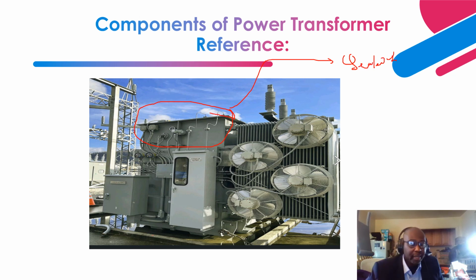As you can see over here, the top of the transformer is sealed, and inside that you have oil. On top of the oil is a cushion of nitrogen that has been put over here to pressurize and create a positive cushion pressure. This is the enclosure for the nitrogen bottle, so you have connections inside here that go there to provide that nitrogen pressure.